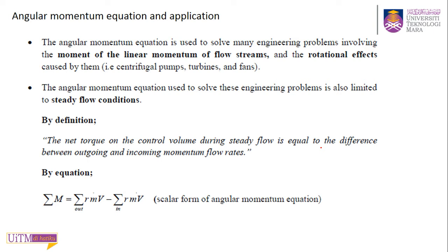And the angular momentum equation used to solve these engineering problems is also limited to steady flow conditions, only steady flow. So by definition, the net torque on the control volume during steady flow is equal to the difference between the outgoing and incoming angular momentum flow rates.